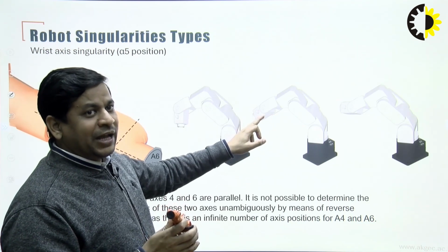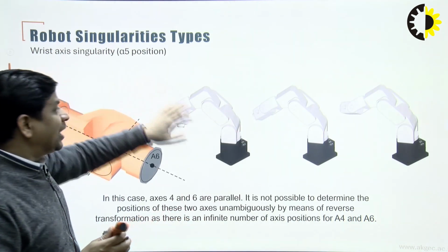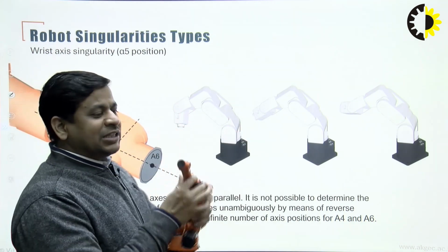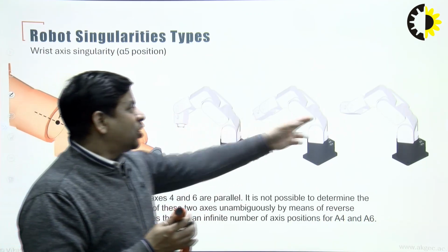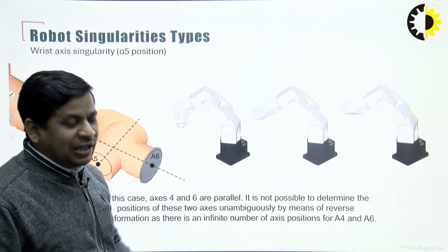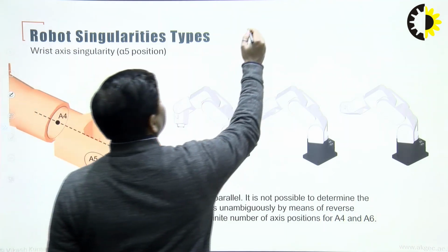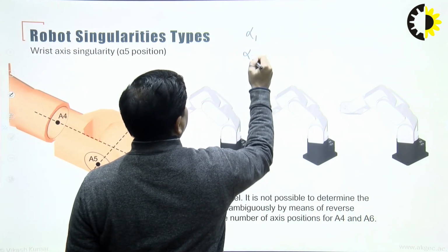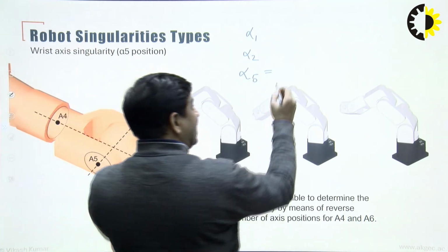So because of that, the robot also faces the problem of wrist root singularity. Always avoid this straight position; either go with a downward or upward position, so that you can easily avoid this singularity.